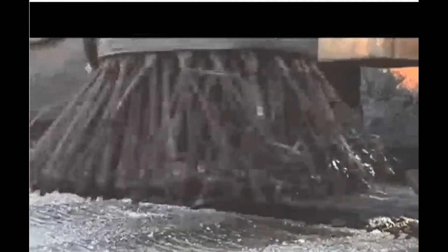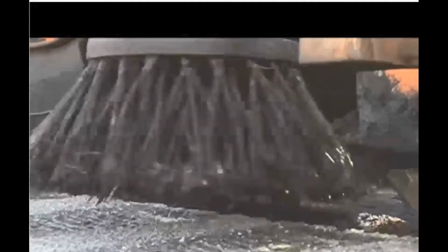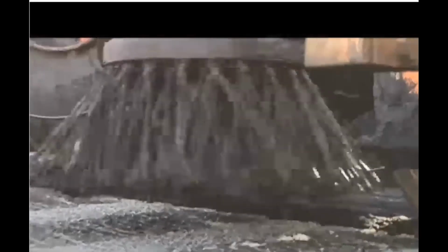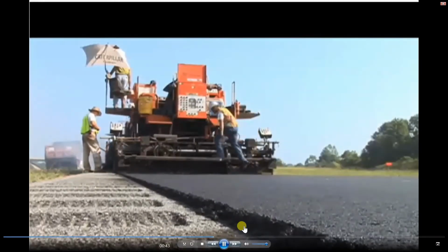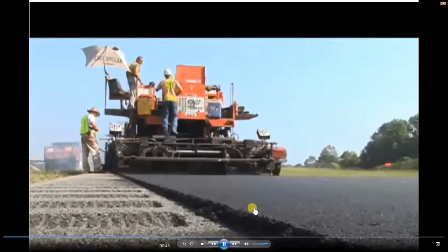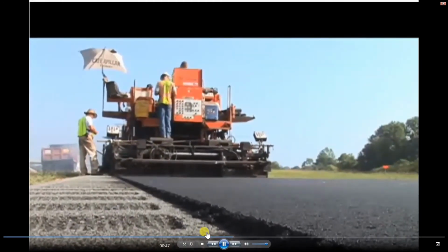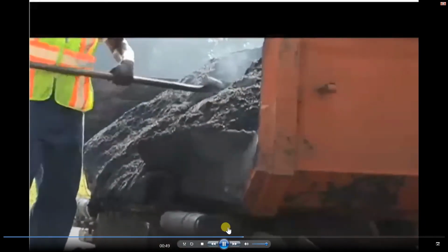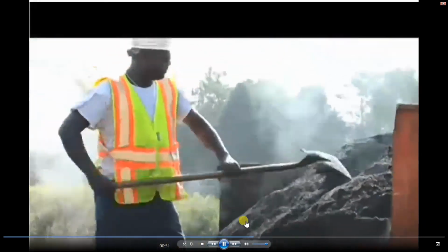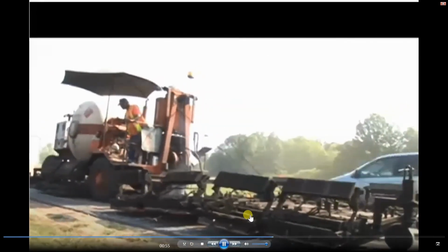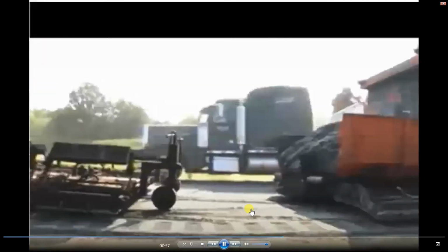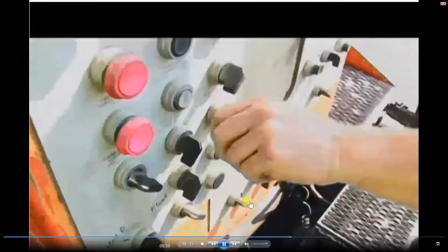No tack coat is required due to the excellent thermal bond created between the remixed pavement layer and the underlying pavement surface. If the recycled pavement is going to act as the finished riding surface, some public transportation agencies require that a small percentage of virgin asphalt mix be added to the recycled pavement prior to replacement. If a separate riding surface is to be applied, the 1.5 to 2 inches of recycled pavement can be remixed and put down without adding any additional virgin asphalt mix.